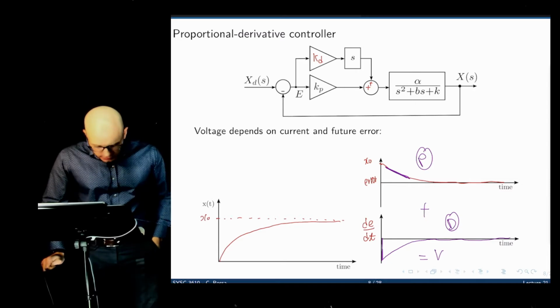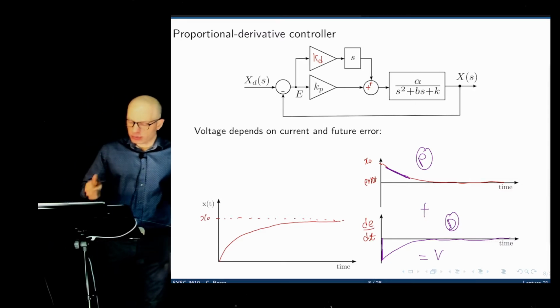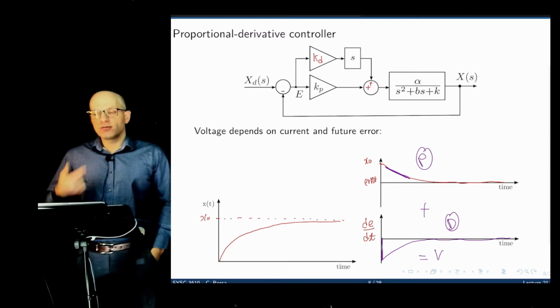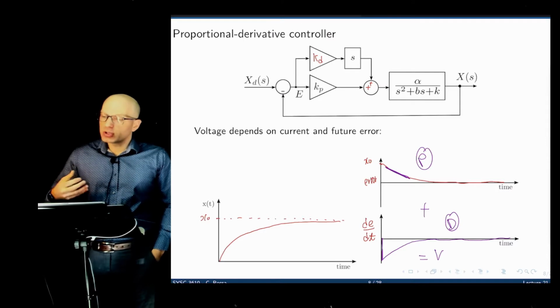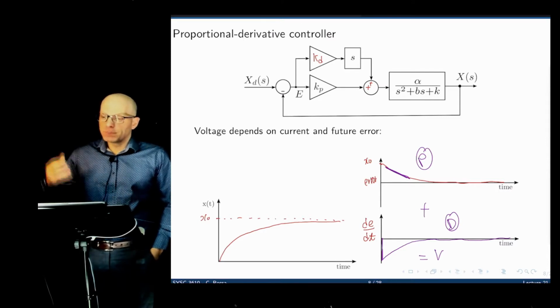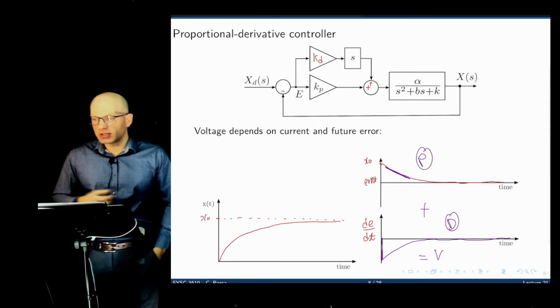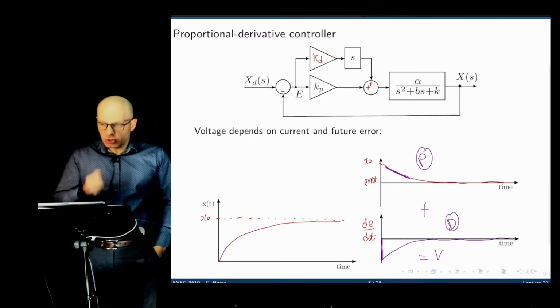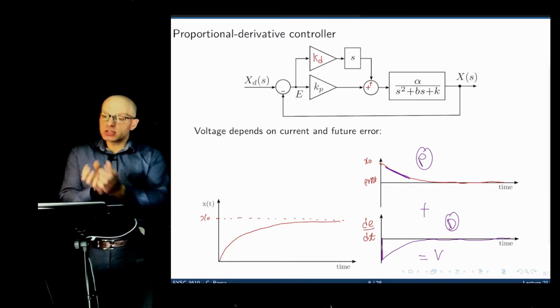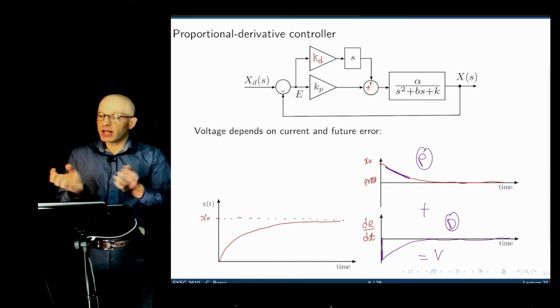And why is it negative? Because the derivative of the error, which is decreasing, gives a negative voltage, which in other words means we are going towards the destination we want. The error is decreasing over time. The control action we are taking is effective in decreasing the error. So if that is the case, let's decrease the control action so that there is no overshoot.